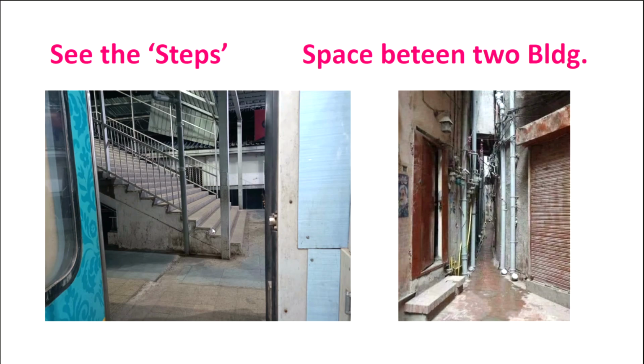Initially he might have started on the right course, but subsequently there was some problem, and due to that these risers are not properly constructed, possibly because he needs to have that much tread. Suppose 300 is required, and he wants to adjust to that 300, and possibly the layout is not done properly, and you land into such a problem.